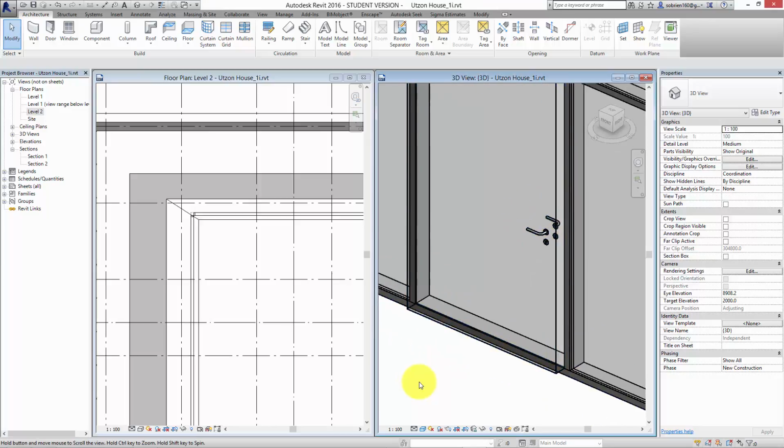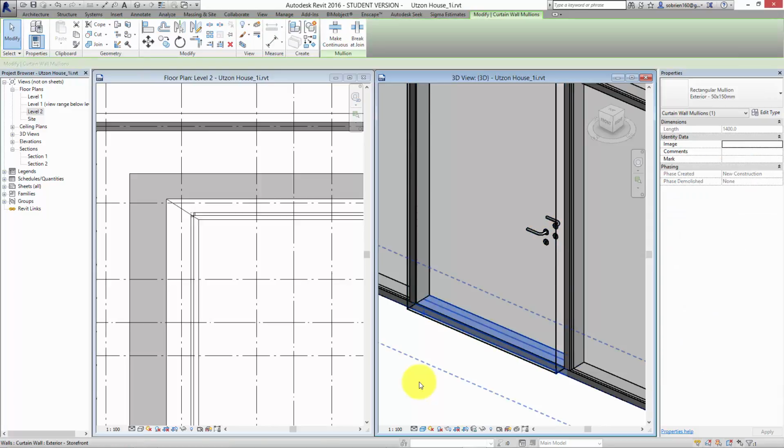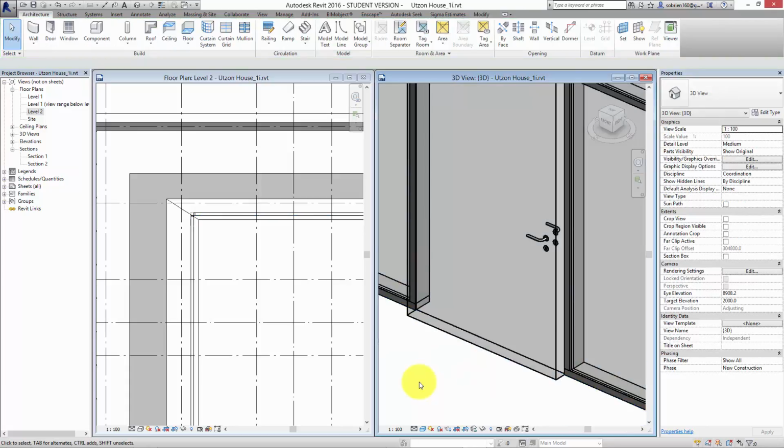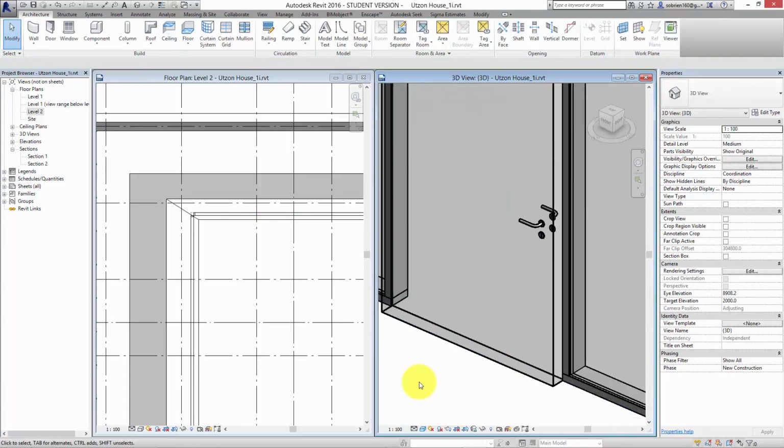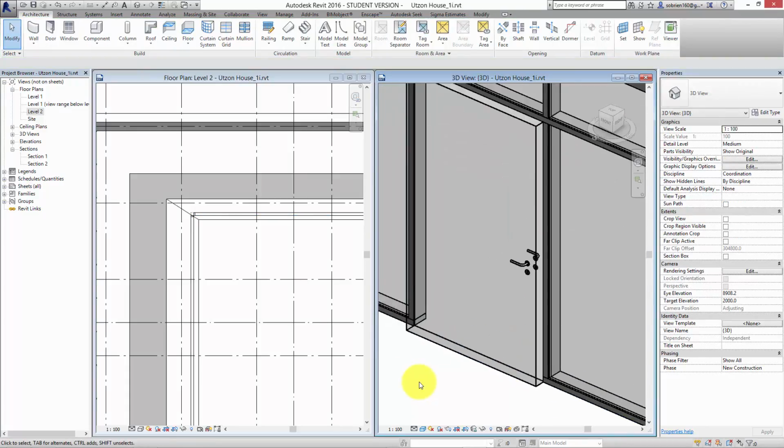We then would want to maybe remove the frame underneath the door. It's possible that the curtain wall comes with a frame under the door, if it comes in one piece from a manufacturer, but it's also possible it doesn't. So if you ever need to do that, you can again just roll the cursor over it and tab until you select the individual frame, and then you can just delete it by pressing the delete button. And you can see it stretches the door down to the ground to take account of the frame being taken out. Simple enough, isn't it?